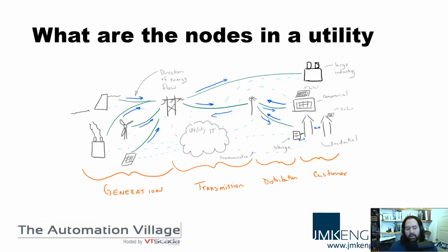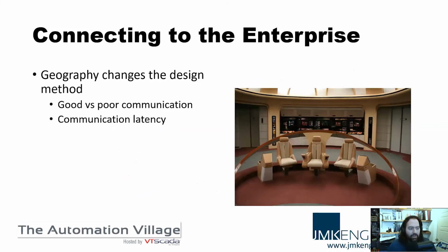So now that we have the OT figured out, how do we connect that to the enterprise? How do we connect that to the overarching utility, the business? Well, this is where we're going to include a new piece of equipment. It could be a traditional RTU, a remote terminal unit, but typically those are operating on DSL links, leased line, or microwave networks. They don't necessarily have the bandwidth to handle the amount of data that we want to be transmitting in the modern era in 2020.